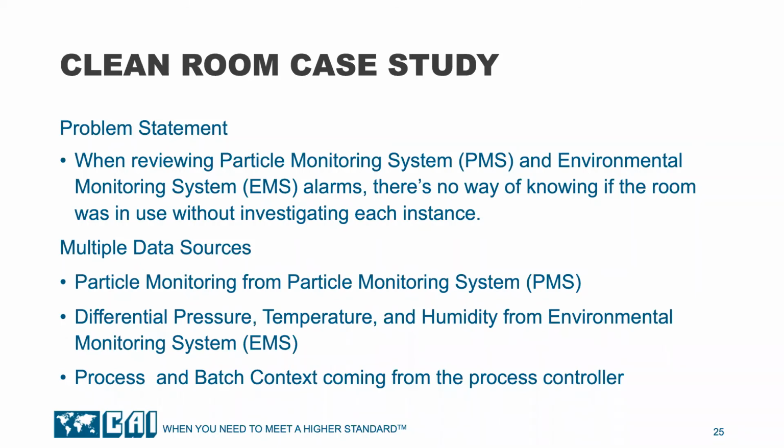It took a thorough review of paper, batch records, and logbooks to demonstrate to the auditor that the rooms were not in use or were out of service being cleaned when the alarm conditions were active and the rooms were out of specification. Since we had a robust data infrastructure, a continuous data historian, OPC servers, and a contextualized data historian, I was able to propose that we contextualize all the DP measurements for the clean room and combine them in the production report for the processing equipment that was located in the room.